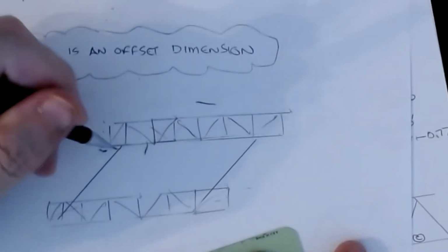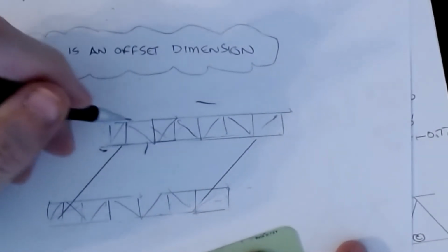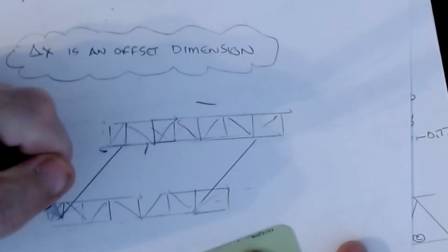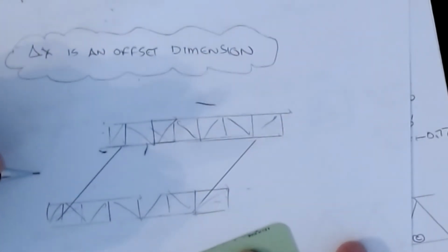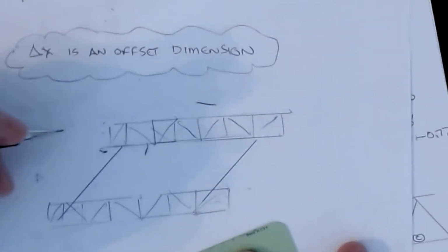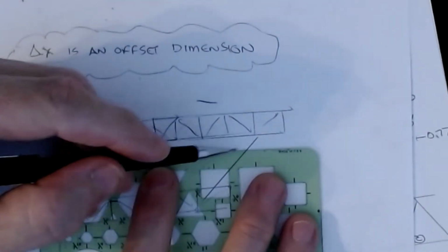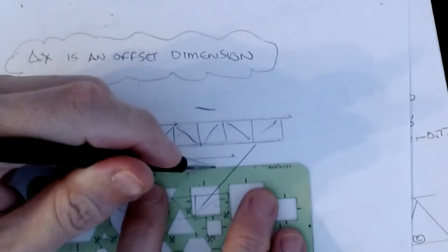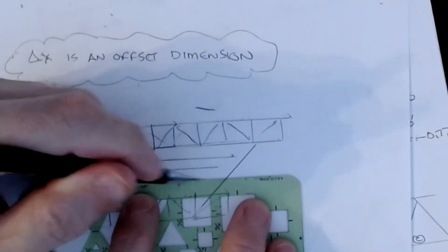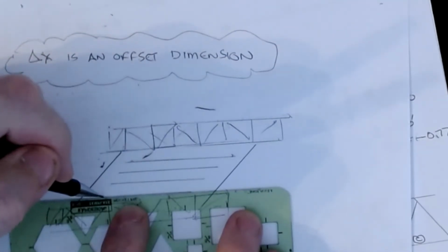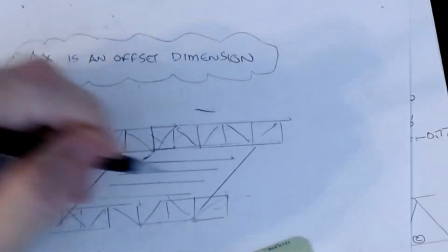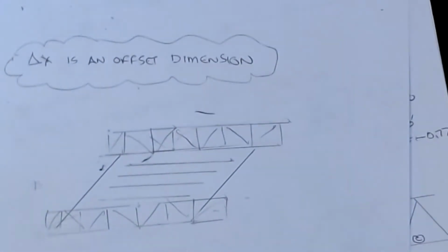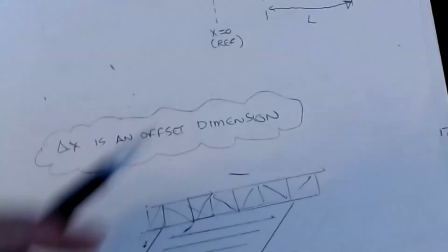And so what happens is the truss is what is used to span the river or the valley or the gorge or whatever. And then there's these girders that transfer across on here. Now the road deck is a result of a vehicle moving down this way. Well, in between these girders will be a series of secondary beams, okay, down the length of the path that basically transfer the load from the slab and any vehicle out in the middle out to the girders. So that's how we were able to ensure that I get point loads on this particular truss. All right, sorry for the long-winded explanation, but this is a valid kind of idea.